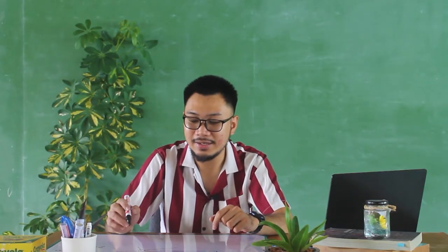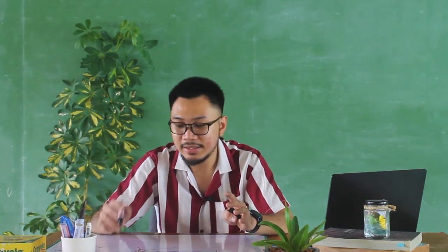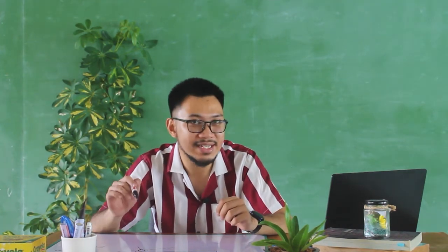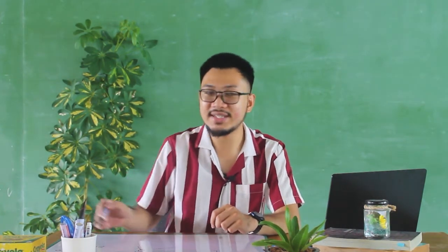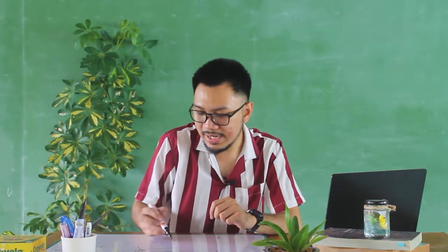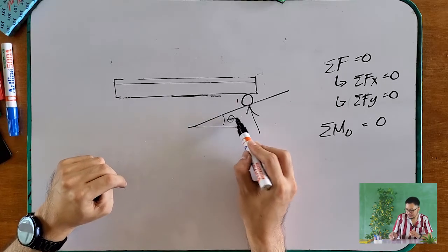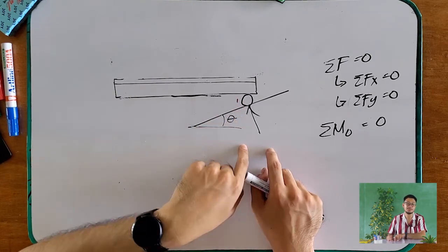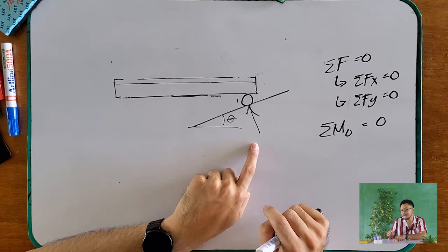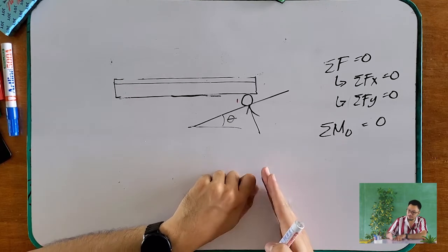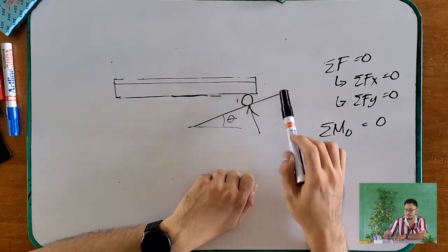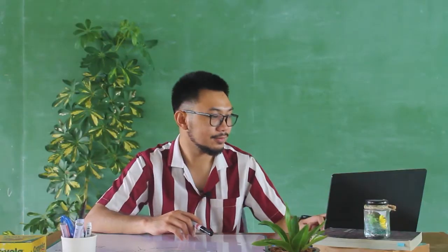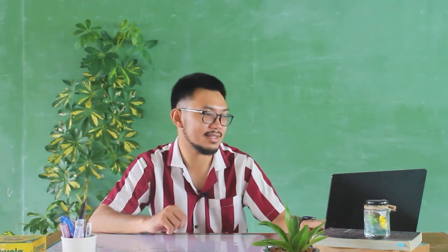So take note of that. What I said earlier, our roller is on the y-axis when our surface is horizontal. But if it is at an angle theta, then the direction of the support reaction of your roller or rocker should be directed normal, or perpendicular, to your surface. Okay? And etc. The others have similar concepts to what I discussed.